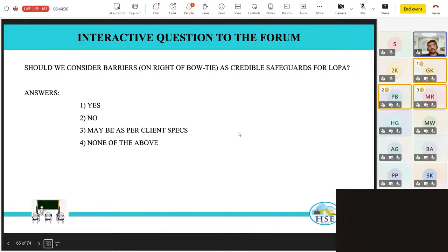And many times, just a couple of months back, we did this for Stanlow Refinery. They had not configured their fire and gas detection to trip any of the inventory or any of the supply lines. So basically, we provided that as a safeguard. You can see, in one of the case studies we'll be studying, we insisted that they use that as a tripping point and tripping safeguard, and then that was considered as an adequate protection layer.